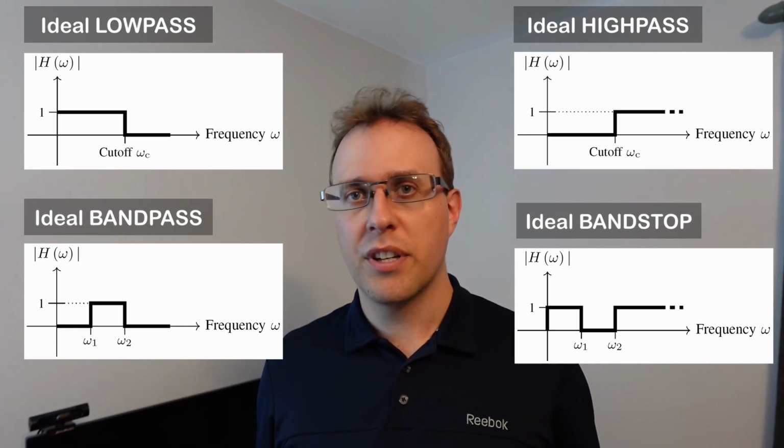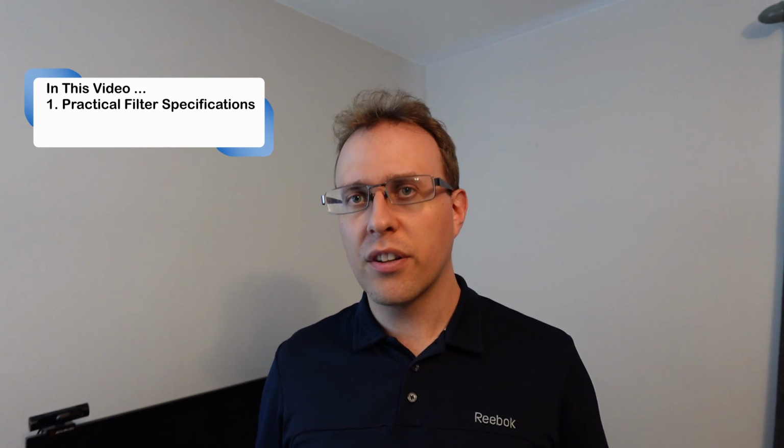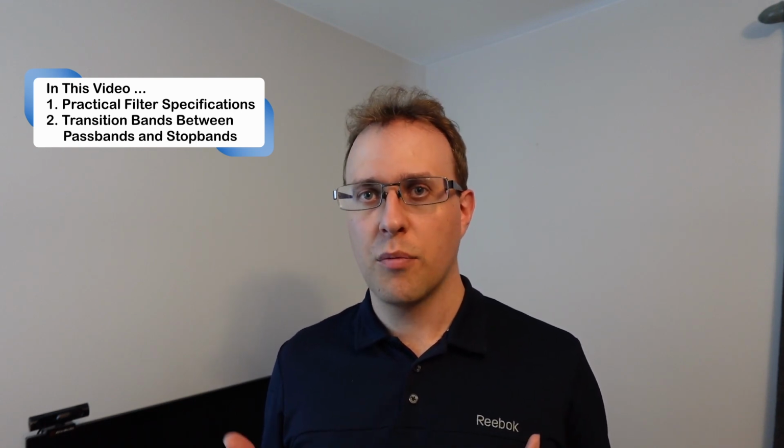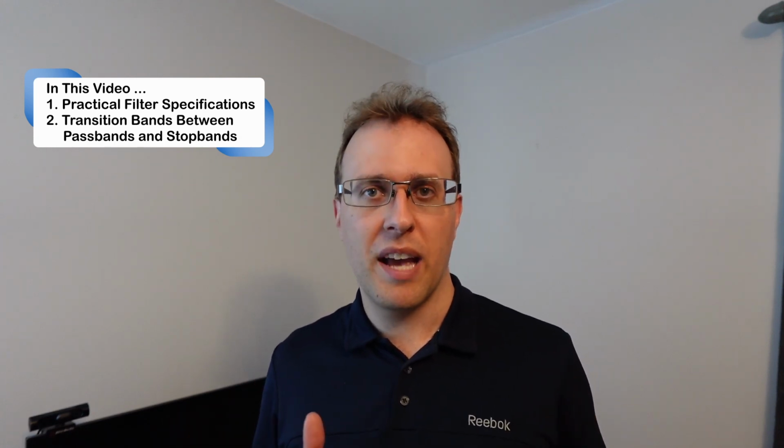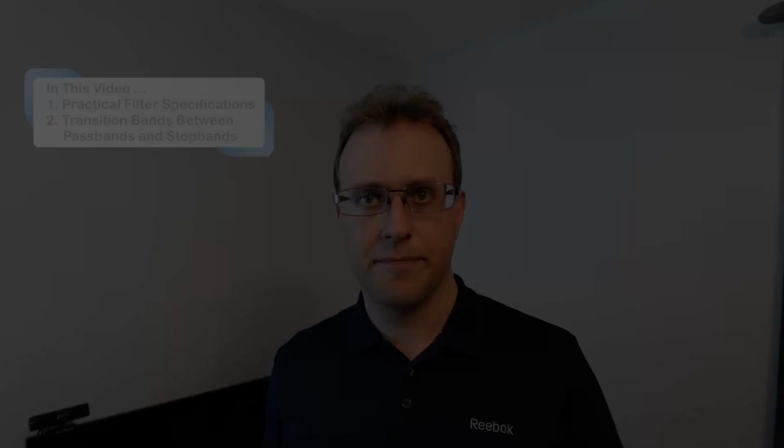In this video, we're going to talk about how practical filter specifications are defined, particularly in the frequency domain, and we're going to introduce the notion of transition bands, which are used in the frequency domain to define spaces between where the pass bands and the stop bands exist. Since we tend to define filters in terms of the frequencies that they pass through, we usually find it useful to define a filter specification in the frequency domain.